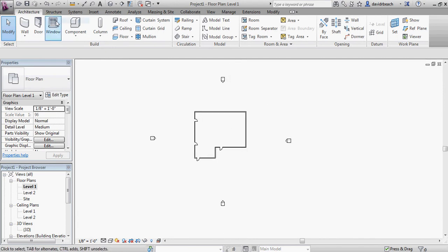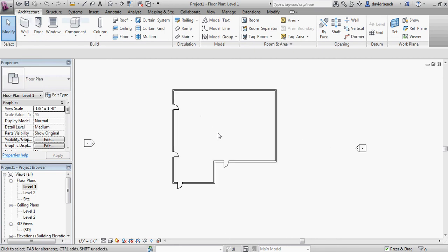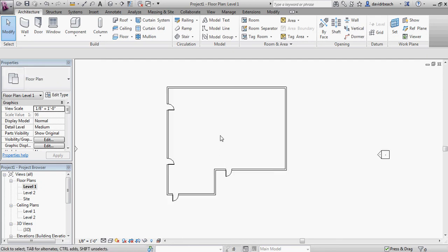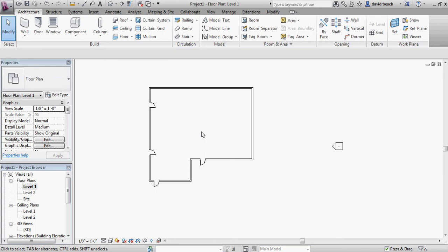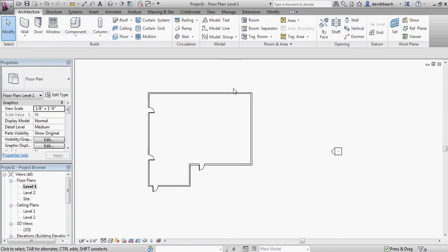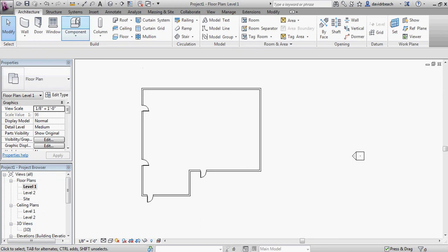So, the reality is you'll use this core set of tools and the curtain wall tools and the basic creative tools, the roof tool, floor tool, you'll use those very often, but they're all really easy to manage, they're easy to work through. The tools that I actually like to start teaching first are the component tools. How do we start creating custom shapes and things inside of the program so that we can really design whatever our imagination desires? So let's just launch that tool set here.